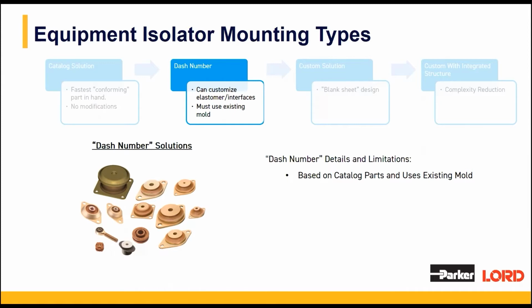However, our molds have lots of flexibility to make modifications that we can do. For example, we can change the elastomer we squirt between the metals, or we can change what metals we use instead of aluminum, stainless steel, whatever it may be that we need for a specific application. The coatings that we apply to the metal can also be modified, or finishes.